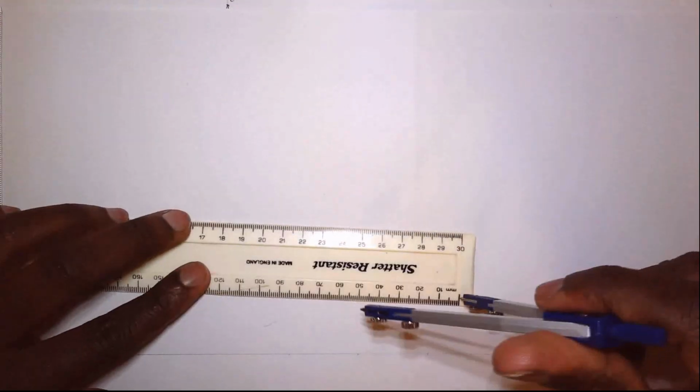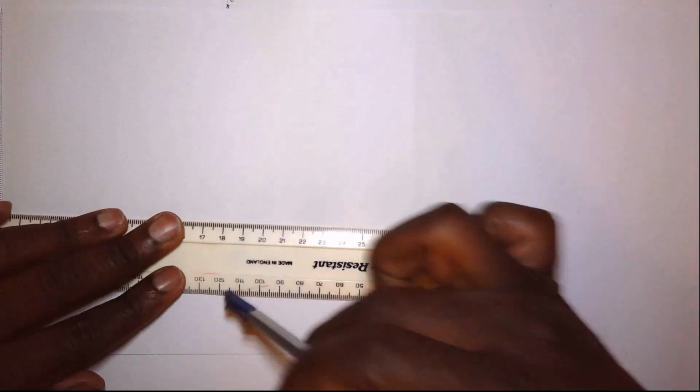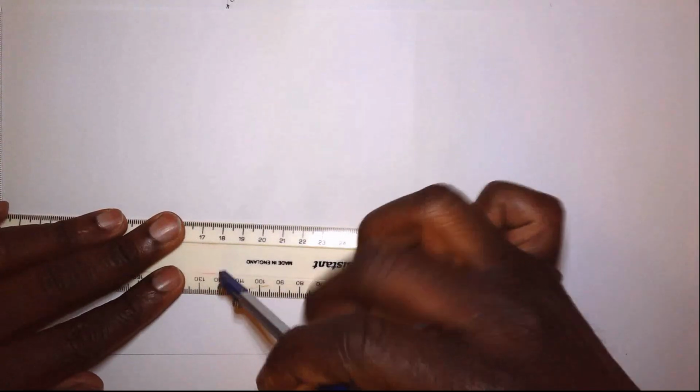So what does exercise 7 say? So this time we're being challenged to construct a right angle triangle, base equating to a length of 120, so that will be our AB, and one of the base angles is equal to 30 degrees. So this should be a fairly straightforward affair. So let's start off by scribing our base. So we've got our base, get our compass, and this time we're going to open to 120, as shown here.